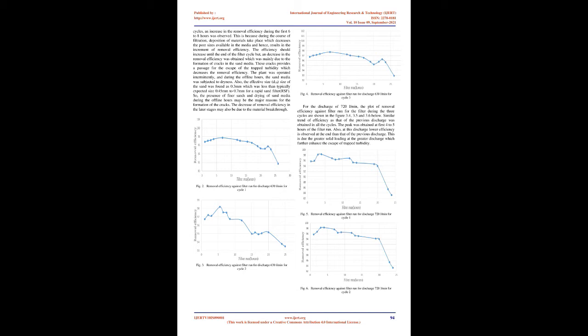Tube settler. The water from the flocculator is then sent forward for the sedimentation process. For sedimentation, a single unit of tube settler has been provided. The tubes are 50 mm dia high-density polyethylene, HDPE, pipes. The tubes provide larger effective settling areas due to which the area requirement for the tube settlers is much less